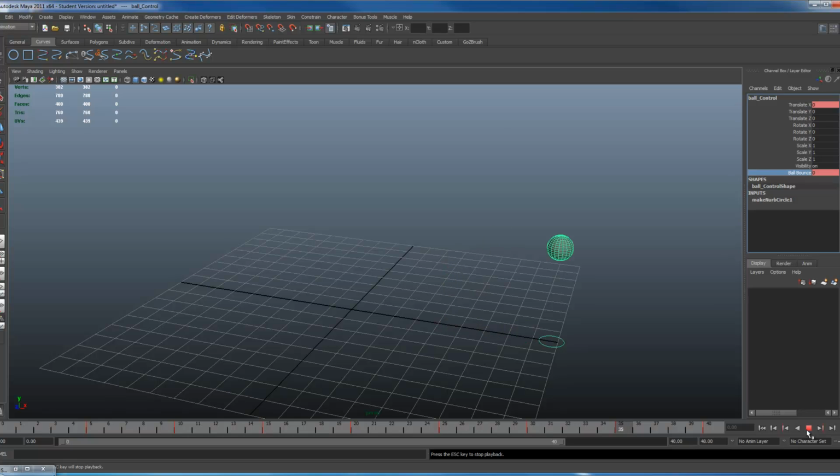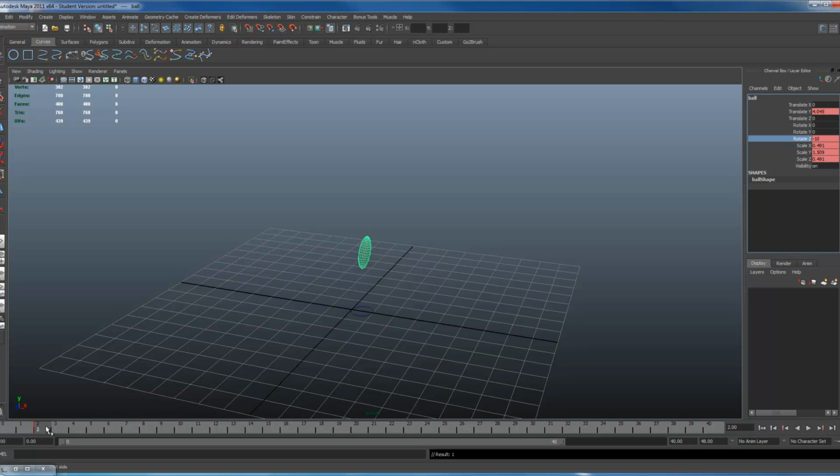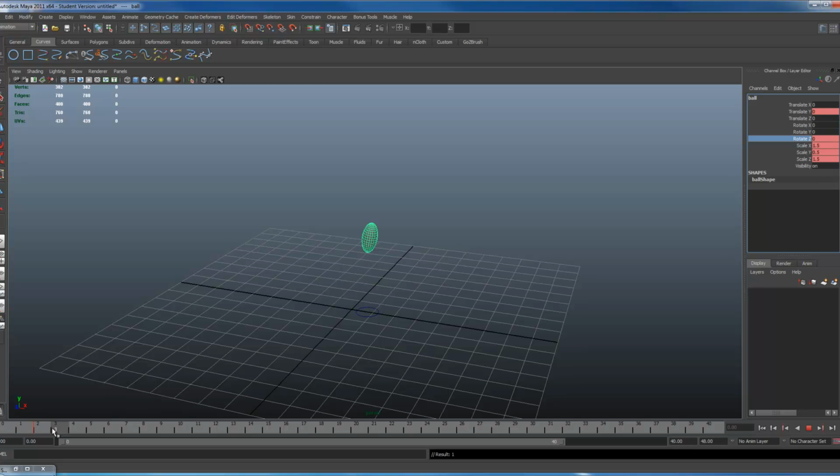I can also tweak these animations, because technically speaking, all I did was have it go up and down. What if you wanted to have a slight lean between each of these? You can technically do that. Go inside and just slightly fine tune it, and have this thing rotate, and key its rotation. Call this negative 10. Key selected. Here. 0. Key selected. I can also turn on auto key, so that way each time I rotate it, it automatically updates.